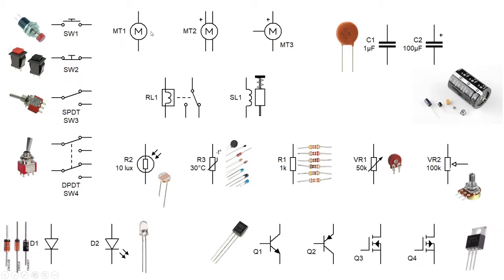But we might have DC motors, a straightforward thing like that. Stepper motors, in this case a bipolar stepper motor with 4 wires coming out of it, or a servo with 3 wires coming out of it. Relays, consider like a switch and an electromagnet, so it'll electronically switch on a much bigger circuit.